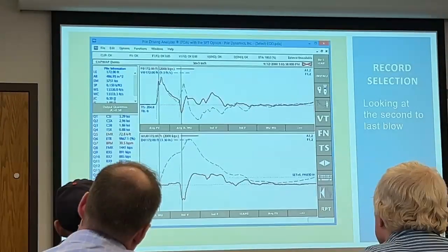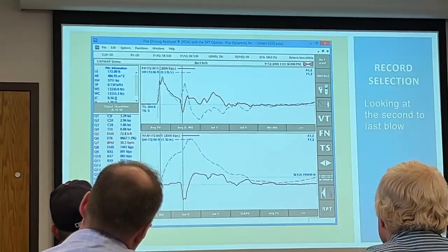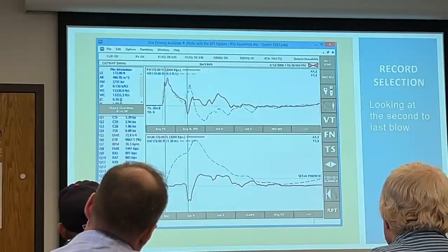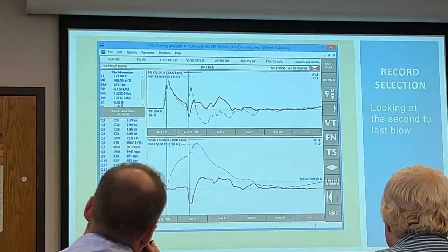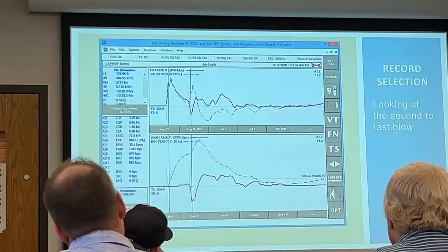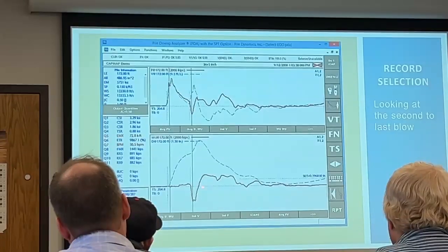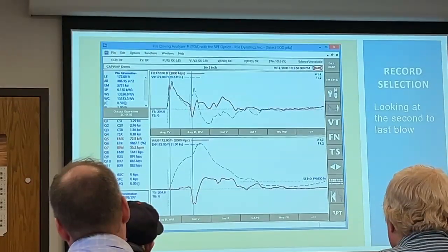So this is similar to what we would expect the result of end-bearing in sand to look like. So the pile toe has to move, but once it moves far enough into that material, the material really pushes back. It's not a fixed end, but it's also not free because eventually we get end-bearing.